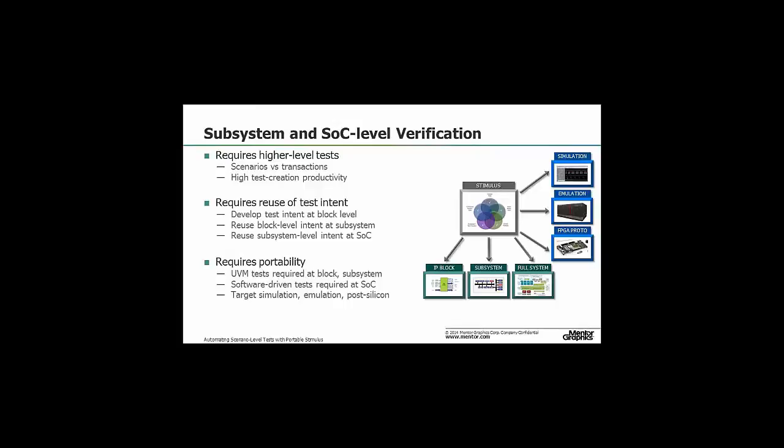Something called test intent also becomes very important. When you develop a block level test, you do it with the intention, of course, of verifying a certain aspect or piece of functionality. And it's good if that can be reused at the subsystem level or even at the SOC level when you move up.